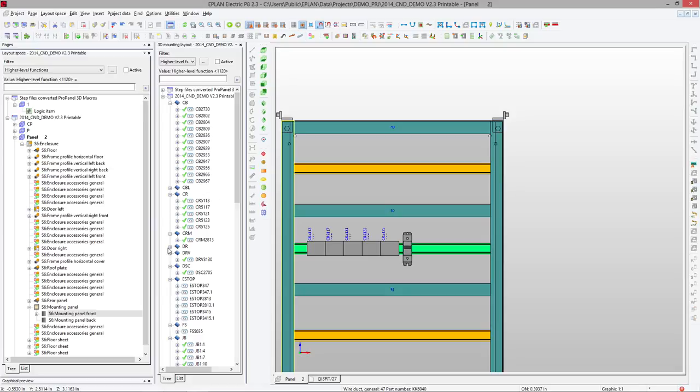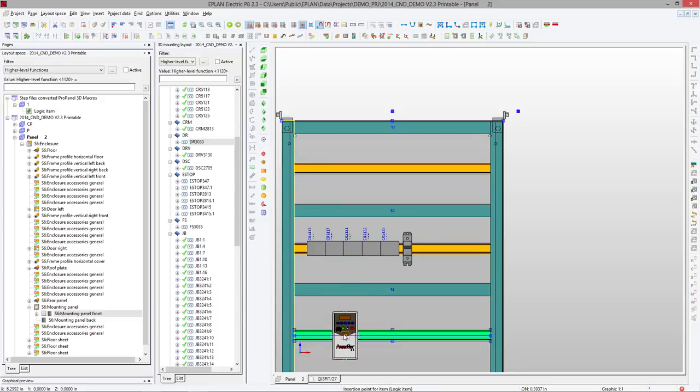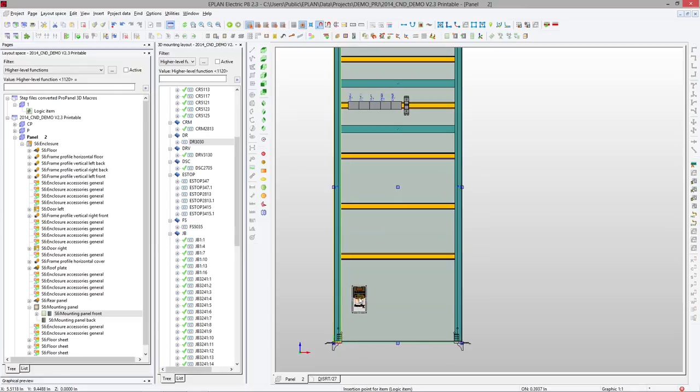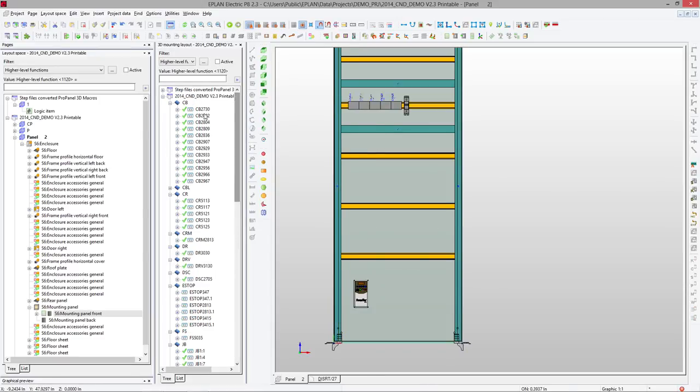What you can also do, if you have some components that are a little bit more complex, is take them and place them either on a DIN rail, or you can move down and place them right on the back plate. That's possible. Okay. Now, from this point on, you can also place components that are not yet in the schematics, because these components were existing in the schematics.